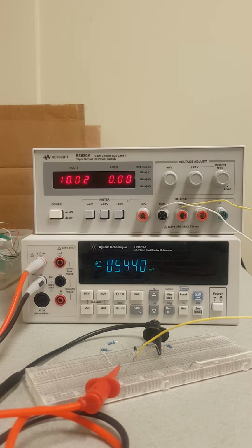However, for continuous monitoring, like for example, the thermostat at your house, we cannot monitor the resistance because the data acquisition systems, including microcontrollers, can only read voltage. So we have to convert the change in the resistance back into a change in voltage. And to do that, nothing better, of course, than our magic Wheatstone bridge.